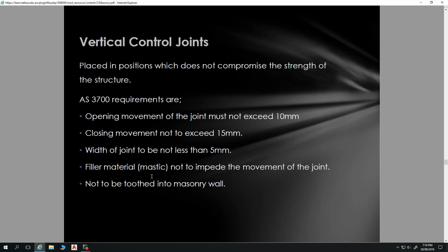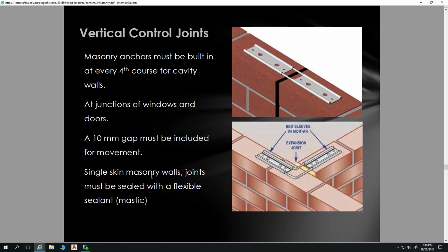That's all kind of superfluous anyhow. When bricklayers do brick control joints, they do them at 10mm. And bricks, when you buy them, hopefully are made by a reputable manufacturer who knows how much expansion and contraction is going to be happening in their brickwork. They've limited that because of their choice of clay, and you're not going to get opening and closing anything near that.